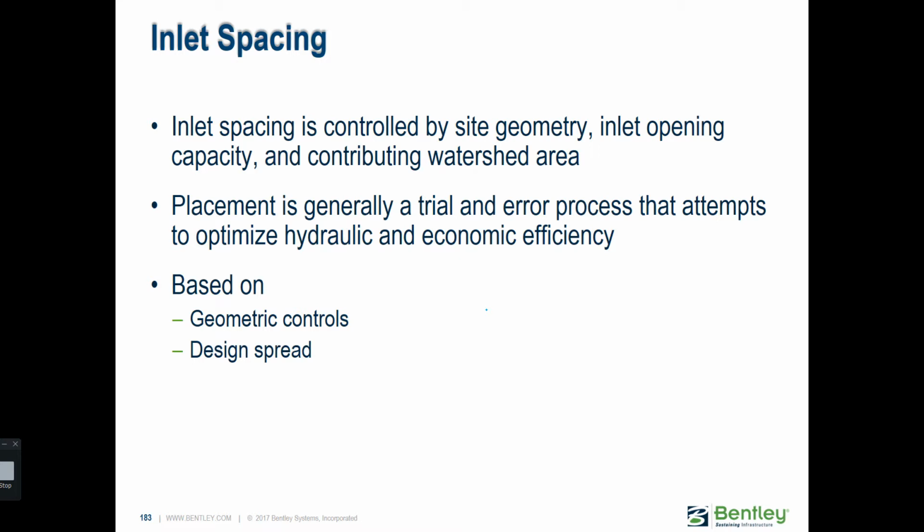Typically, the way to figure it out is trial and error. There are also regulations in many places that say you cannot go for like 100 yards or whatever longitude in a road without having an inlet. So sometimes there's a maximum space that you can go without having an inlet. But more often than not it's a trial and error process.